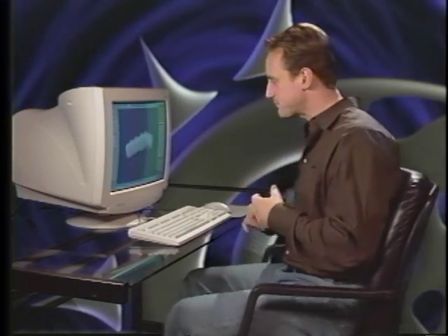It's an important thing to do when you're looking at your model. Don't just look at the solid shaded view. Look at the way the polygons are aligned and make sure those polygons have a smooth flow. It's amazing how much this will actually affect the final render. You get a much better looking surface if your polygons are aligned. And even something as simple as spinning these two quads has really dramatically impacted the overall curvature of the model. Another thing that's important about that is that as I add geometry or extrude this out, any kind of surface anomaly I have at the base is going to get amplified as I extend those polygons out in the back to create the back side of the hand.